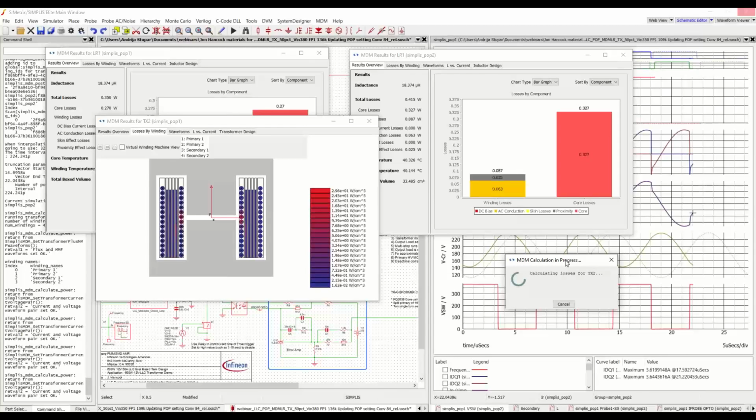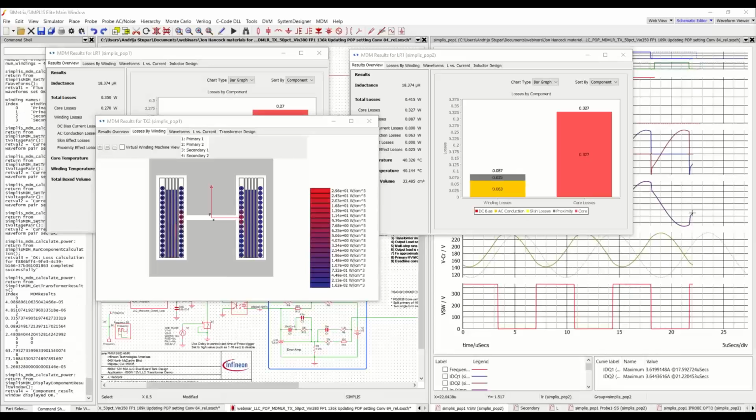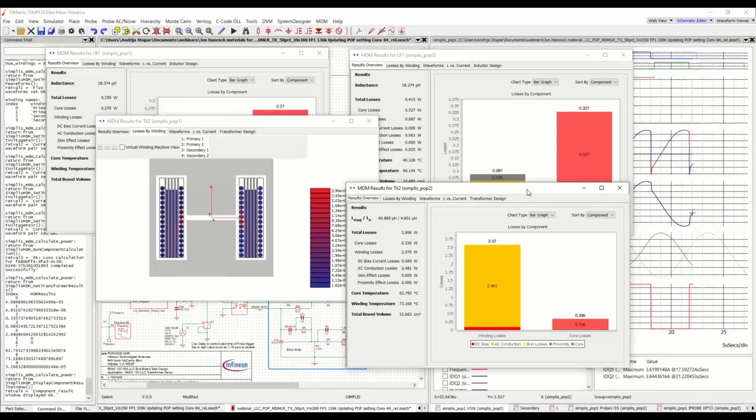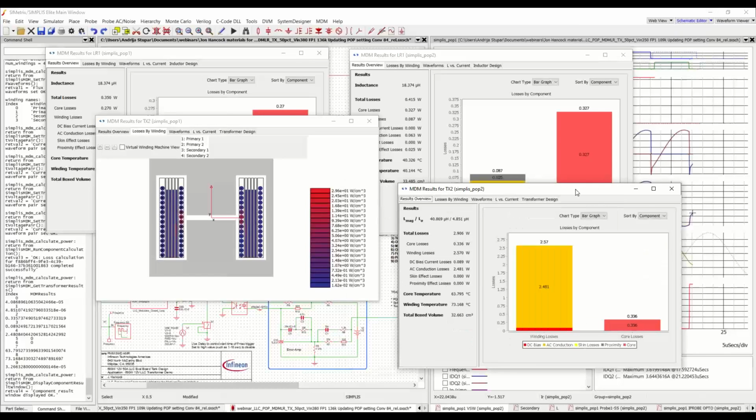We had another question pop up. Is the sim time also related to the thermal modeling? Yes. So here we are doing thermal modeling, which means that the thermal model assumes a starting temperature to be a few degrees above ambient, and then it calculates that temperature and then recalculates those losses with that temperature, and there has to be convergence between the assumed temperature and the temperature that comes out of the thermal model.